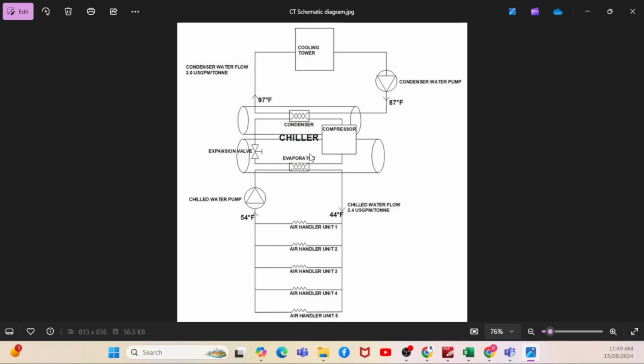As an example, if you go with an air cooled chiller, the maximum capacity available in the local region is up to about 1500 kilowatt. Say you have a project with 15,000 kilowatt. Then you have to go for 10 air cooled chillers, plus maybe one standby chiller. But with the water cooled chiller, you can go with a 6,500, 7,000, or 8,000 kilowatt chiller. So you can go with simply two chillers plus one standby, three chillers instead of 16 chillers.